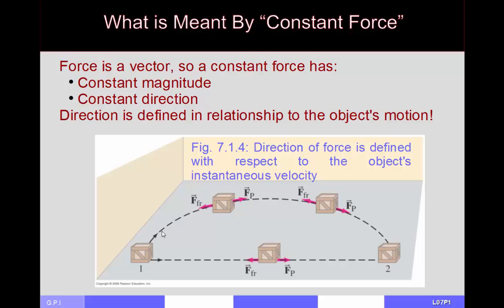So in order to find how much work is done as this moves along this curved path, you'd need to figure out what this path length is, what this parallel component of the force is, and also what the value of the friction is. And basically just multiply that parallel component times the path length and multiply friction times the path length. Subtract the two from each other, and that gets the net amount of work that's done.